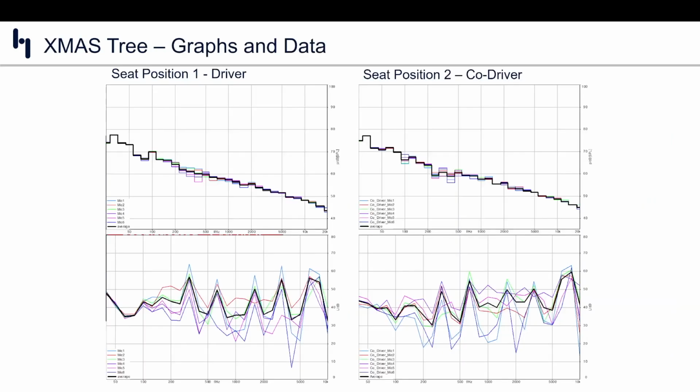Let's start with frequency response measurements. With the 6-mic array, we capture 6 channels at once and of course correct for the spectral shape of our stimulus, in this case a log chirp, so we can see the transfer function of the car audio system for the driver's seat position. This gives us an indication of the audio system performance and something we can compare against other vehicles or other seat positions.